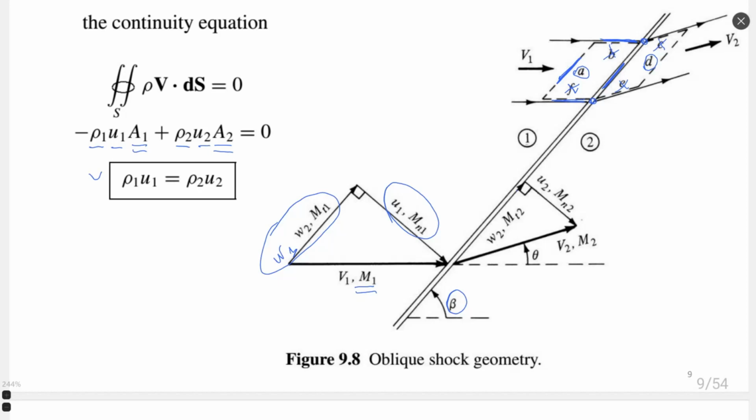But usually we have to say that beta is this, when I write again this M1 here. So beta is the angle between the velocity before the shock wave and the inclination of the shock wave. So it's not always horizontal, and you cannot use the horizontal line as a reference. We always use as a reference the parameters that we had before the change of the flow happened, in such case the direction of the flow before the shock wave.